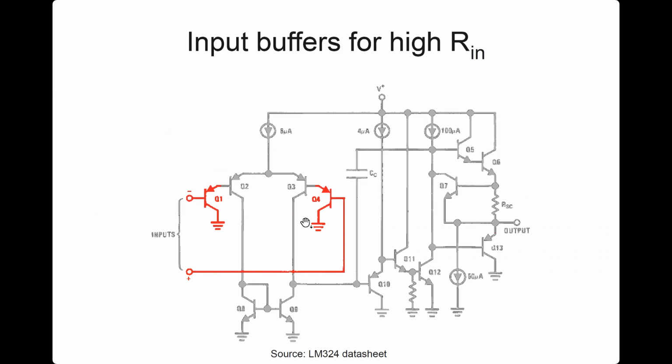So here, if you look at this, what stage is this? Can you recognize? Voltage follower. It's basically a PMOS emitter follower. It's the equivalent of the source follower. Now, how is it biased? It looks like there is no bias current. But the following transistor's base current is the bias current for this. Okay. And I think this is 6 microamp probably. 6 divided by beta of this is the bias current for it. So basically, you get a fairly high but not infinite resistance. Okay. These are like really old op amps with bipolar transistors, but basically that's what it is.